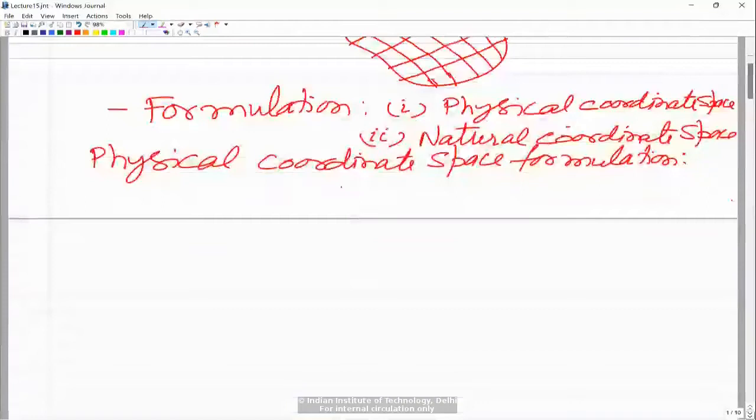If you are using an FE package, you don't have to create a solid. You would just create a line along the center line of the structural component and discretize that. That is what we have done in 1D problems.